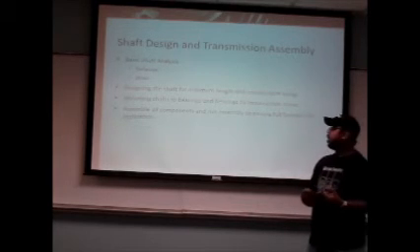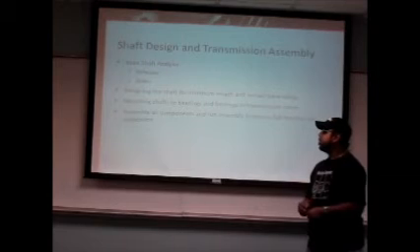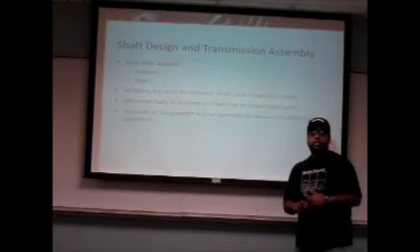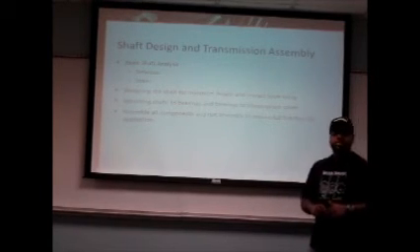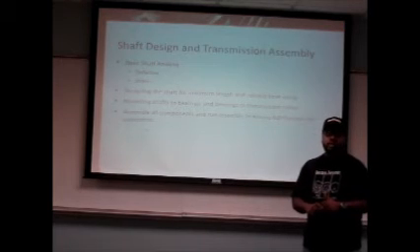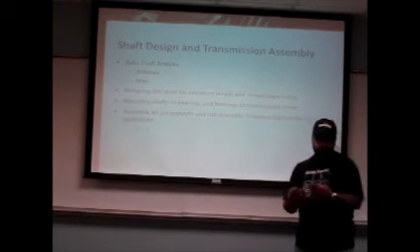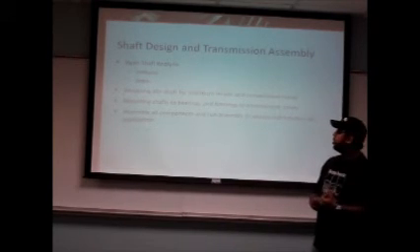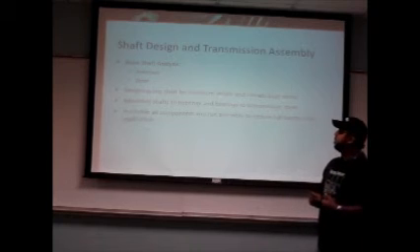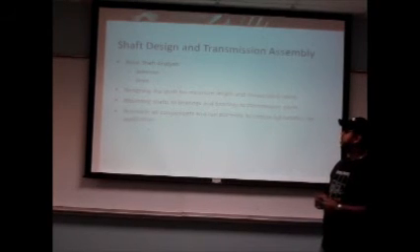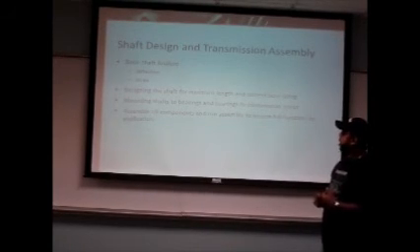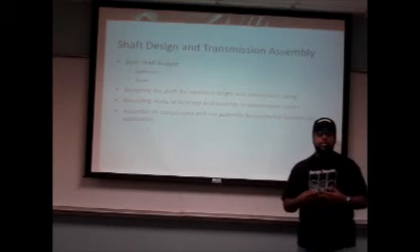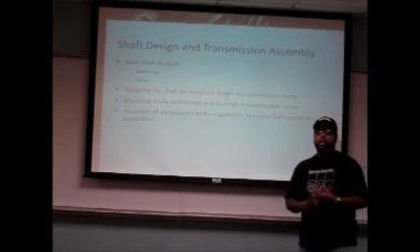We then examined in computational software both deflection and strain under the appropriate forces, and the deflection and strain reported was at a negligible value, indicating that the system is structurally intact for shafts. The entire assembly was put together in 3D software. We used shaft collars to mount the second shaft, and we also made the shafts very short in length to minimize moments.